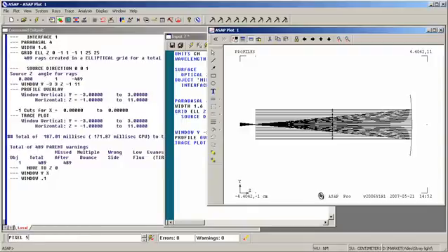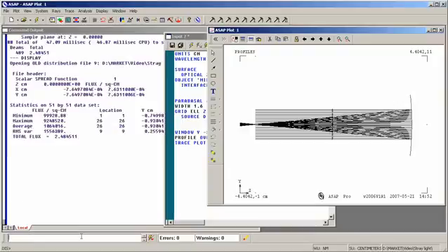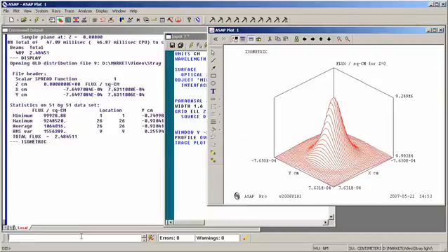Set up a resolution. And instead of doing something like a spot command, spot's position, to show me the geometrical spot diagram, I issue a wave optics command, which is spread normal. Give me this point spread function. ASAP calculates the function and writes it to a file. I use the display command to read the file and an isometric command to actually get a distribution.